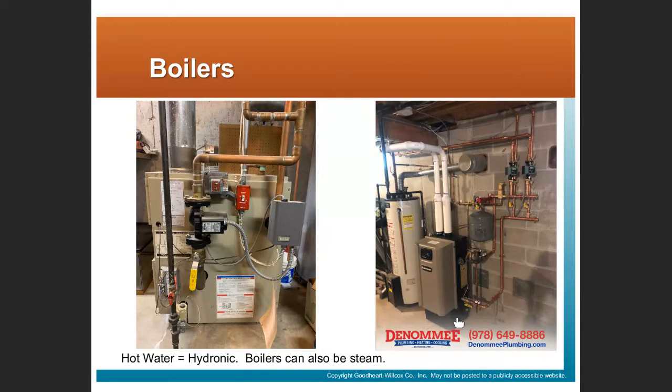Here's another example. This would be a higher efficiency system. How do I know it's higher efficiency? Because we have these CPVC pipes connecting, bringing combustion air in from the outside and delivering the exhaust back out to the outdoors again.